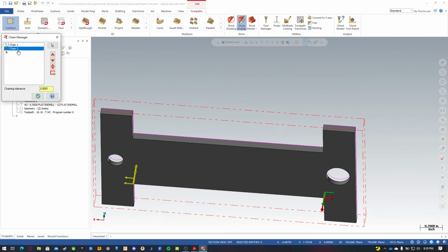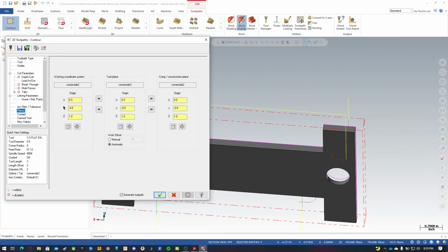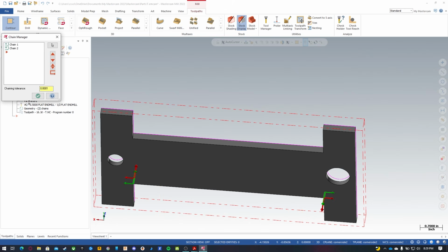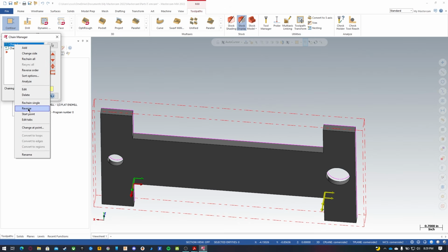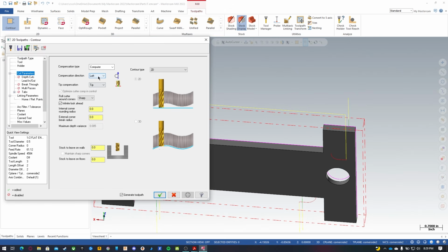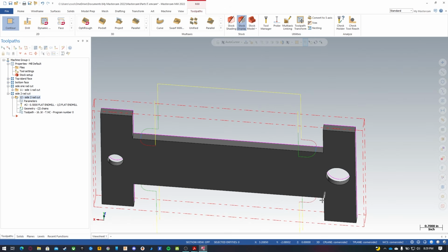So we can add lines, or it's using the previous lines as before. We can reverse those lines by picking our geometry and reversing, and then just double checking that it didn't change the compensation to right hand side. And then we can regenerate, and it's already there, and we're using the geometry from this backside that highlights there, whereas we don't even have it there.